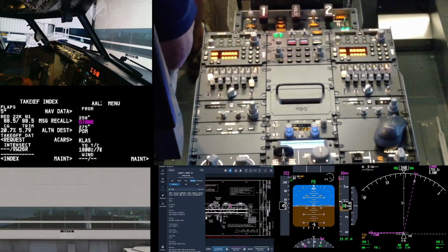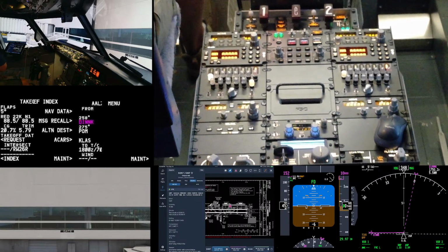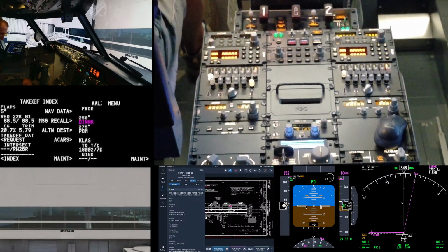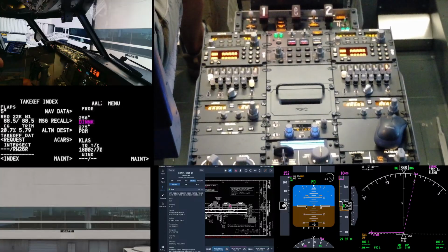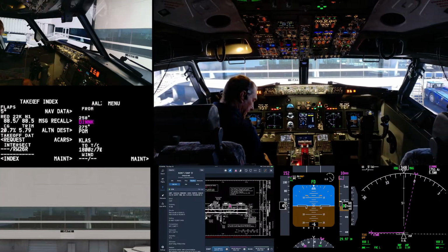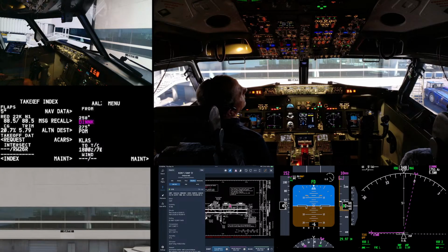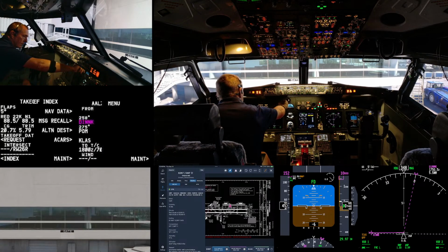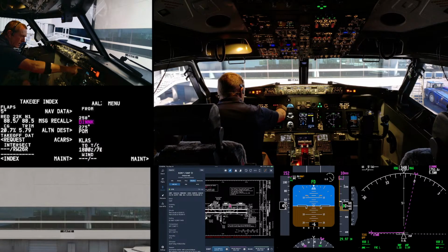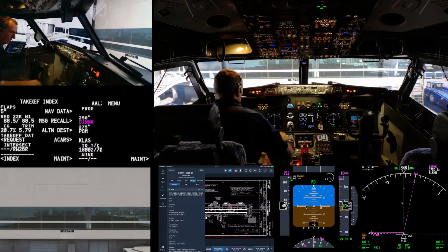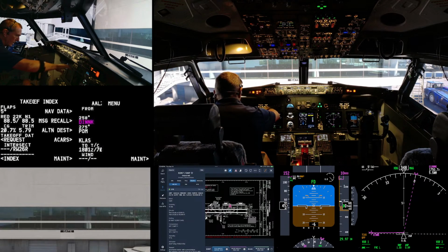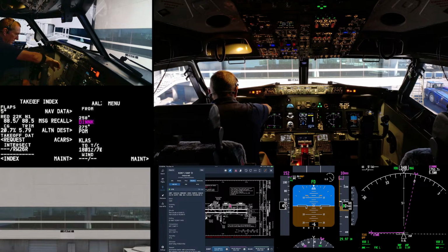So I'm looking at all the blinking lights, if you can see that. Probably can't see it because it's too bright. Put that back to normal. Lights overhead look good. Okay, lights check. Autopilot annunciator, triple amber in 1 and 2. We have 2 reds and an amber, so that's checked. All extinguished. Nose wheel steering is guarded.